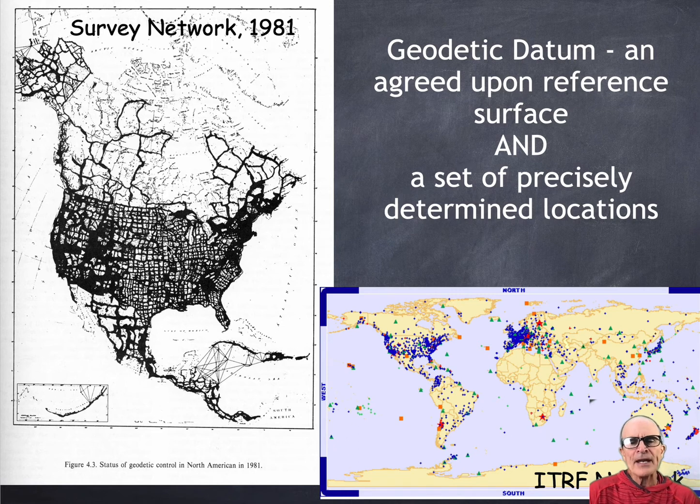But while we were updating it, we were also developing these methods for measuring things more accurately using GPS and that very long baseline array with networks of GPS tied to that array, that we had this period between the 80s and the 2000s where we came out with multiple datums because there were multiple iterations of figuring out where things were, of incorporating tectonic movement.